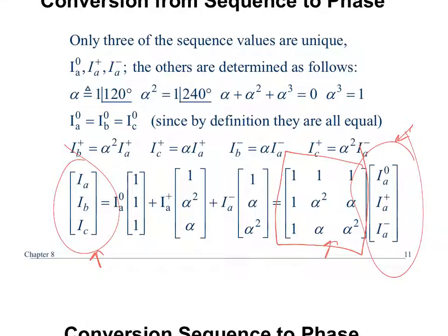We have the line currents, A, B, and C. The relay is not necessarily operating on A, B, C. It might be operating on positive, negative, or 0 sequence components. So the relay will actually convert those into those components, and then it will operate on these. So most of the time, you actually have these. You need to check and calculate these.